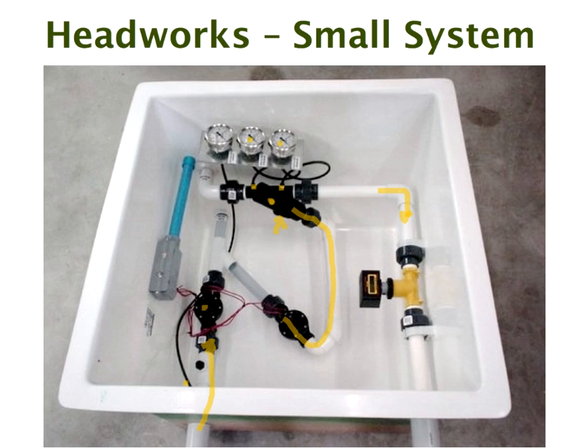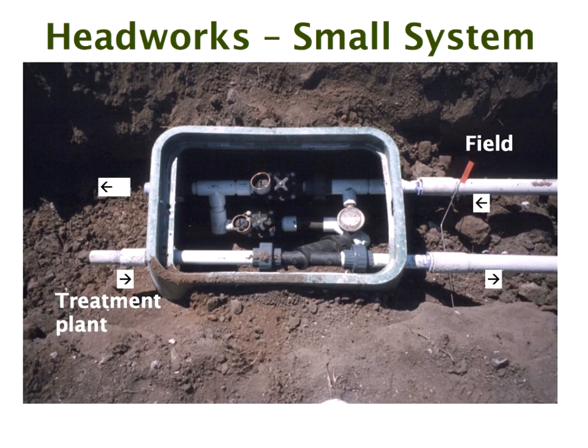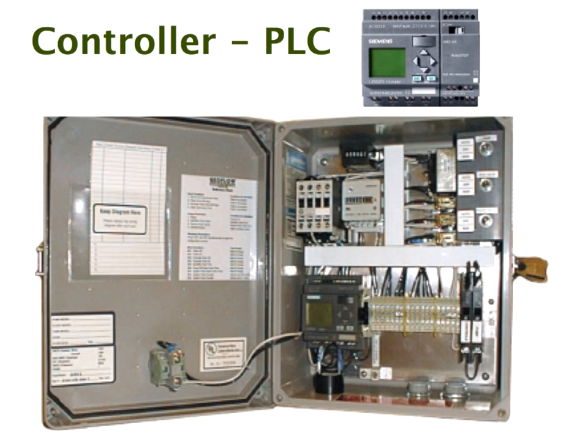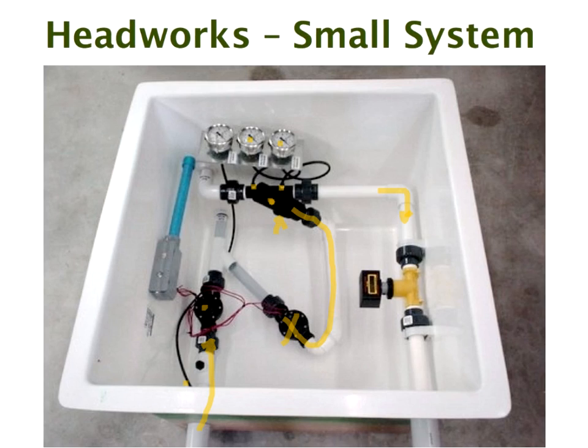I'm just saying, you do get some systems, low-cost systems where you have a manual valve here instead of a solenoid valve there. Actually, let's go back. Okay. You have systems where this is a manual valve, and people will come out every 6 months and open and flush it. Is that a good idea with a screen filter? No.